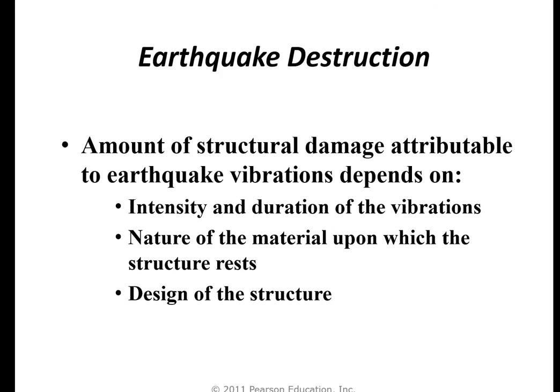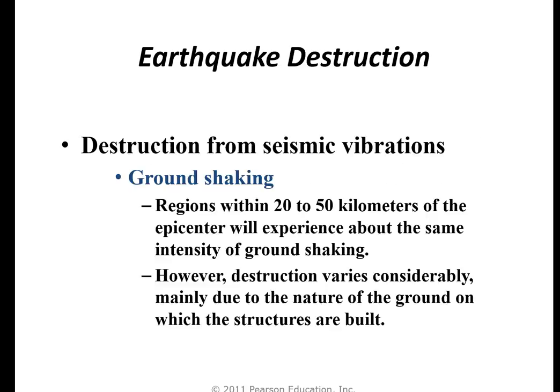Now let's talk about destruction in an earthquake. The amount of structural damage attributable to earthquake vibrations depends on the intensity and duration of the vibrations, the nature of the material upon which the structure rests, and the design of the structure itself. Regions within 20 to 50 kilometers of the epicenter will experience about the same intensity of ground shaking. However, destruction varies considerably, mainly due to the nature of the ground on which the structures are built.